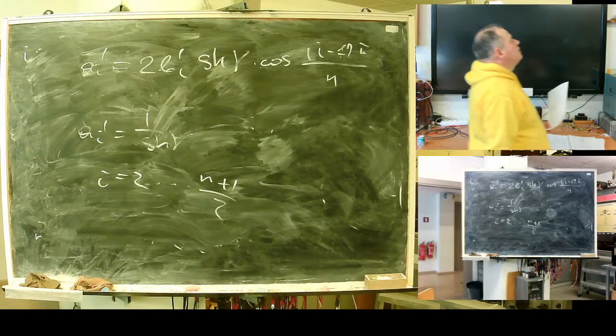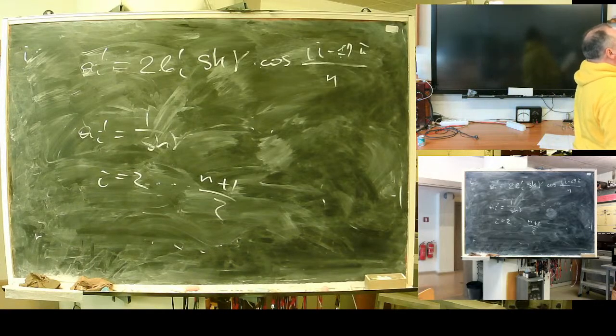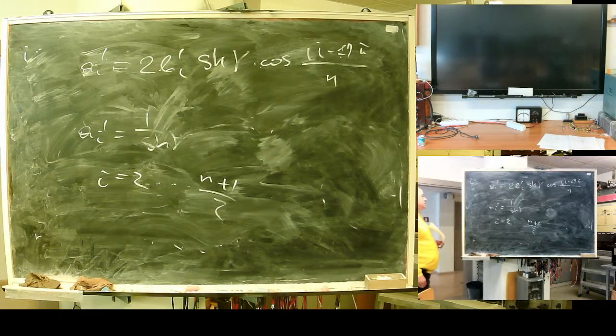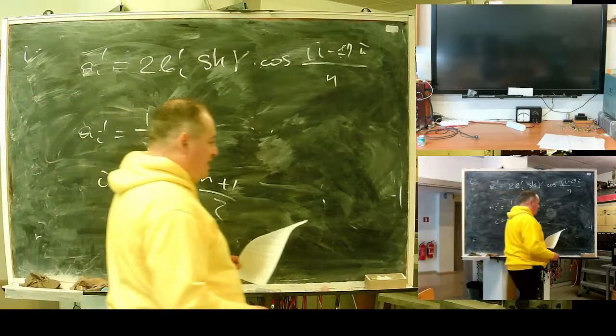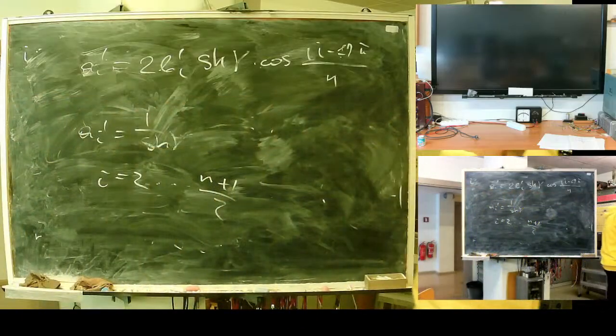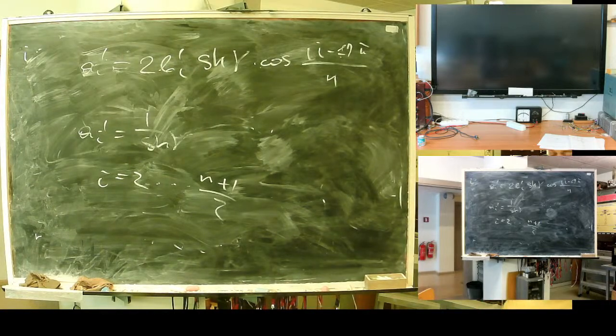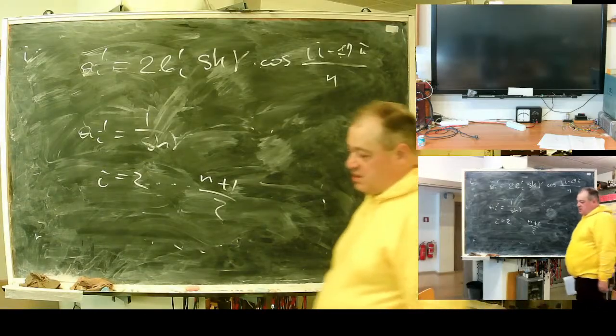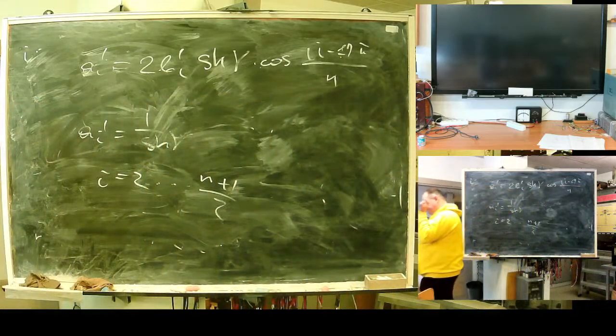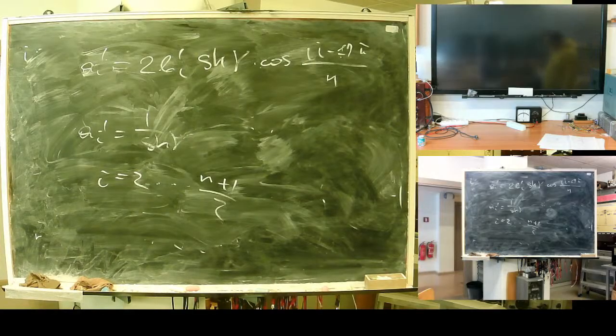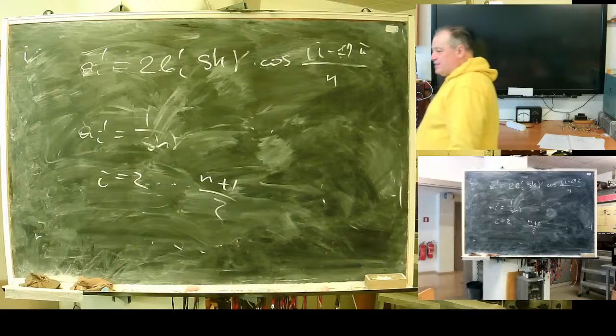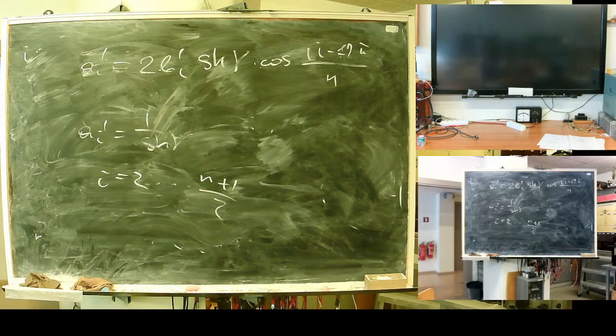What can be done with Chebyshev filter? One trick: there are special designs for Chebyshev filters with zero points in the area just above cutoff frequency. Cauer design is a special Chebyshev filter with zero points just above this rejection frequency. The Cauer design ensures the fastest possible transfer from go to no go.